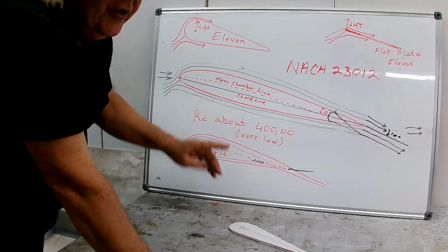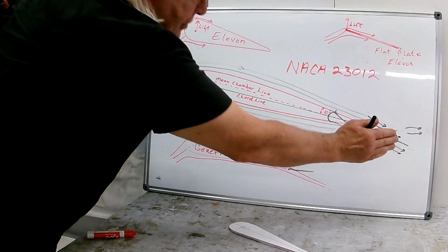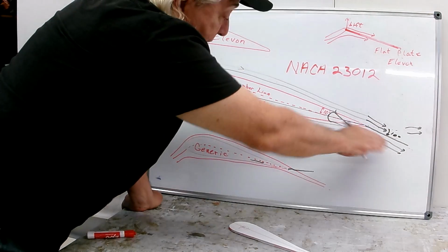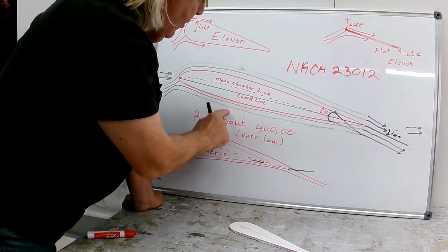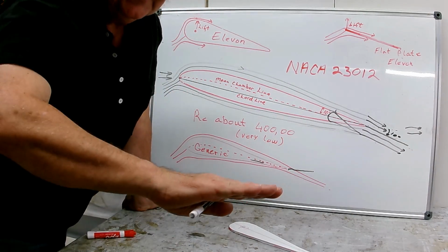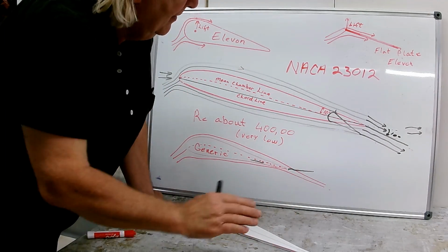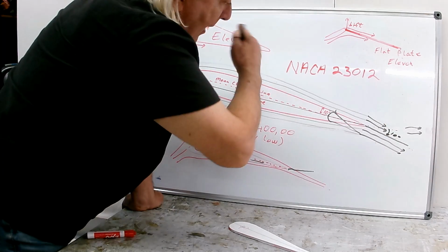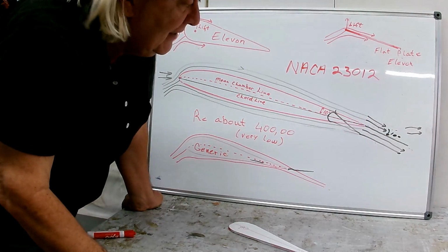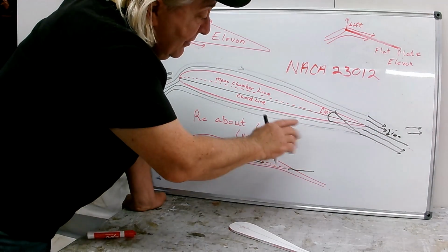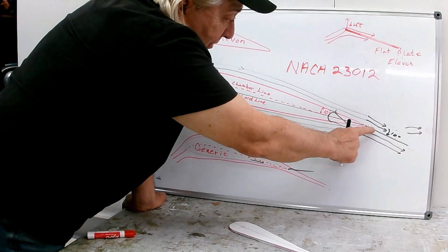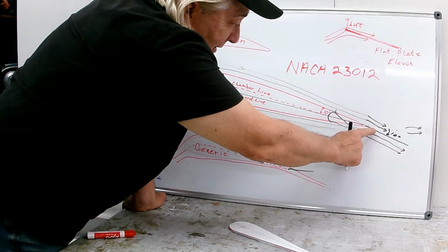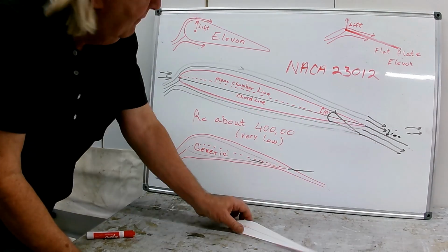And when you do that, as far as the whole airfoil is concerned, when it goes down, the airfoil has more camber in it. That means this airfoil is generating more lift. More lift here causing a rolling or a pitching moment. And if I deflect it up, I'm uncambering or reflexing the airfoil, and that's going to cause a loss of lift on this airfoil.